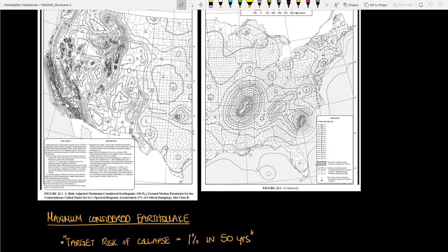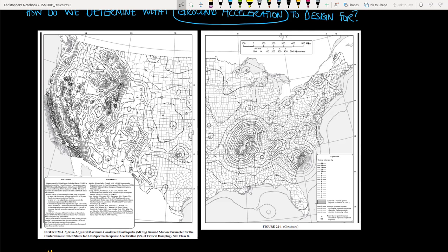What we should note with this map is the areas with closely packed lines. Of course, everything on the west coast here is the obvious place that your eye will be drawn to. But there are also somewhat unexpected areas as well on the east coast. These areas are where engineers need to pay particularly close attention to seismic design and detailing of their structures.